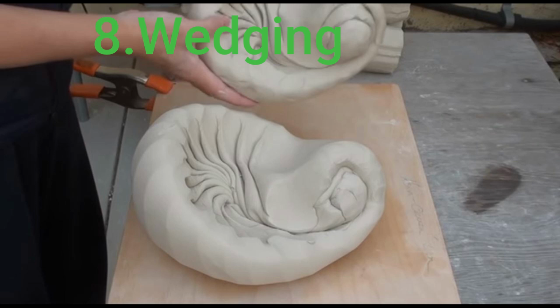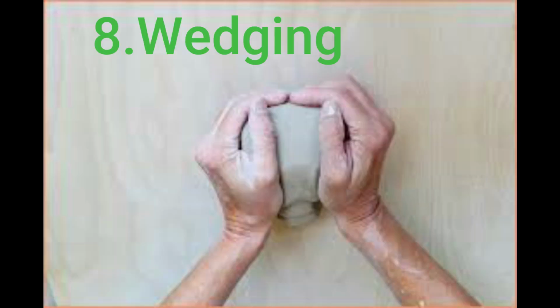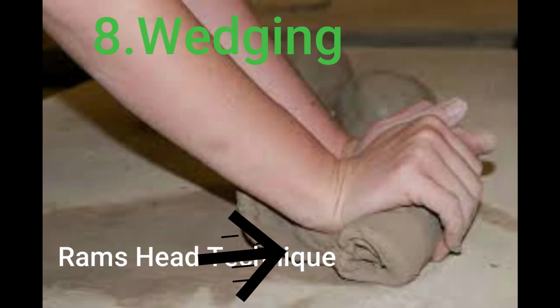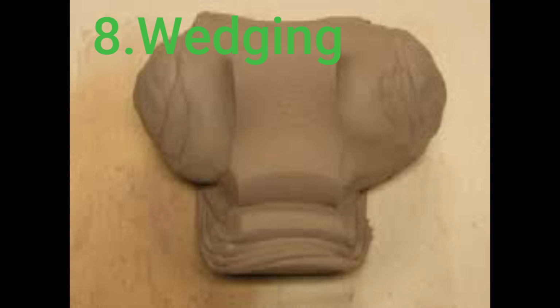And there are two main techniques. The spiral technique is where the wedging is done in a circular manner, and ram's head, where the clay is struck down hard onto a surface and then pressed into a slab, gathered into a lump again, and then the process is repeated. Expelling air is important because those air bubbles are able to cause cracks in the clay when firing.